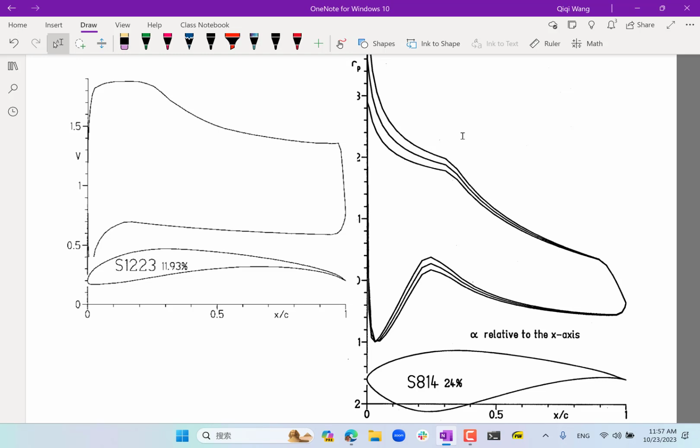So basically by looking at the pressure distribution, you can already design good high lift airfoils that prevent flow separation based on what we know about boundary layers. All right. So this is almost the entirety of our viscous flow section. Next lecture, I'm going to mention a little bit about three-dimensional boundary layers and start to get into compressible flows.